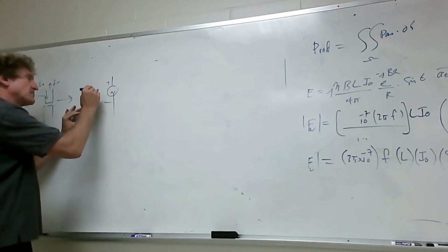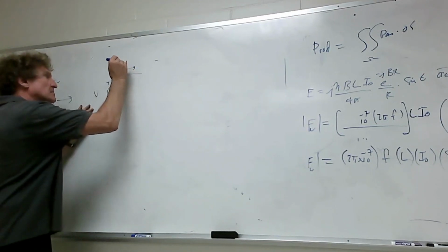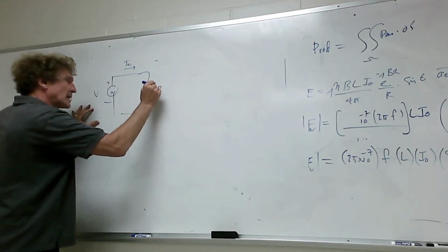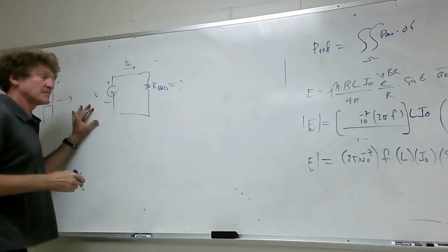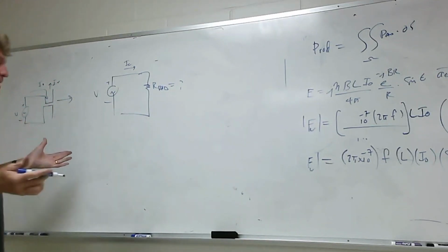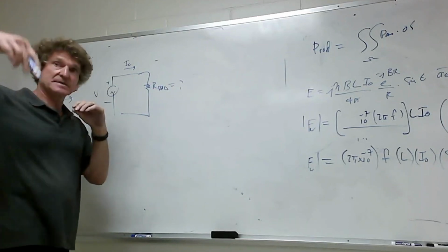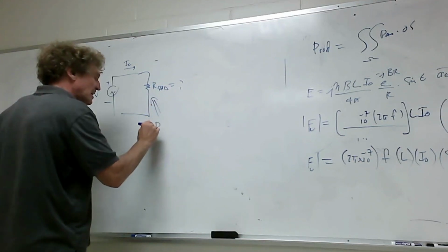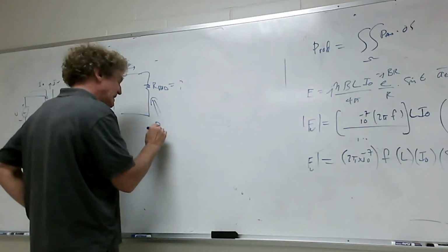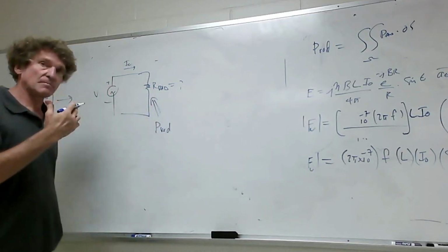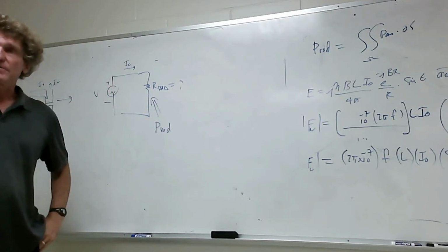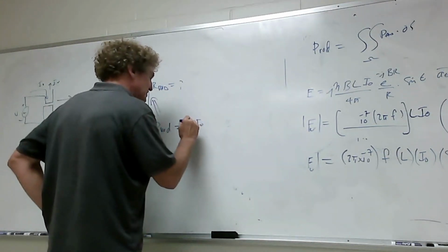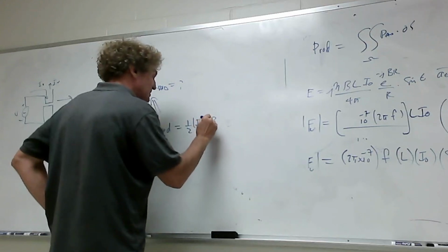So we say that we have some voltage giving rise to some current, but we need the effective radiation resistance of that. Well, anytime you got a resistor and you got current, if it's AC current with a peak value of I naught, you know that the actual power dissipated here, or radiated in this case, because that resistor is representing the transfer of power from current into photon, is going to be equal to 1/2 magnitude of I naught squared times R rad.